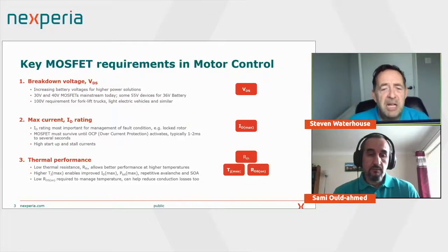Obviously, as you keep driving the MOSFET with 0 volts on the gate, and that linear mode starts to limit the current, then the voltage developed across the inductances and the connections will reduce, and you turn the MOSFET off. But for a short period of time, we expect it to be in linear mode, and a very high SOA rating is required.